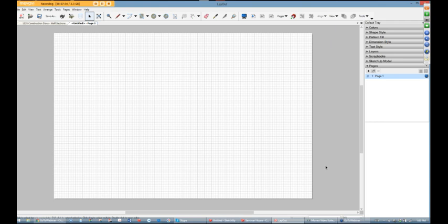And how do we go about doing that? So you can draw in LayOut. L is for line, just like in SketchUp. Now I can draw a line. And you're going to see that it does two things here. It's creating that line. It also has an axes, so you saw it red and green. I'll go backwards on that. So click, it's got an endpoint.